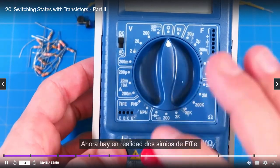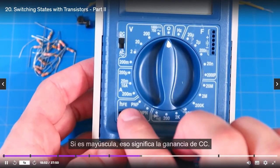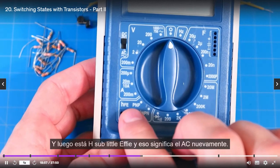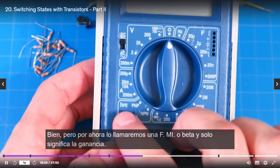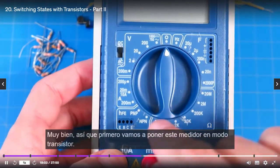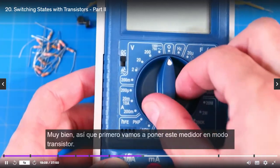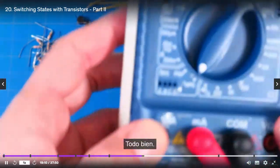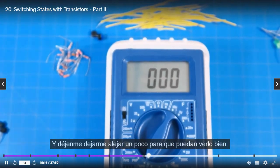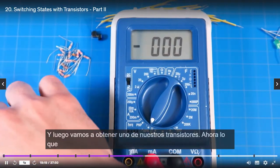Now there are actually two h sub FEs. If it's uppercase, that means the DC gain. And then there's h sub little fe, and that means the AC gain. But for now we'll just call it h sub fe or beta, and it just means the gain. First we're going to put this meter into transistor mode. We'll put it into NPN mode. Let me zoom out just a little bit so you can see that. Okay, there we go.